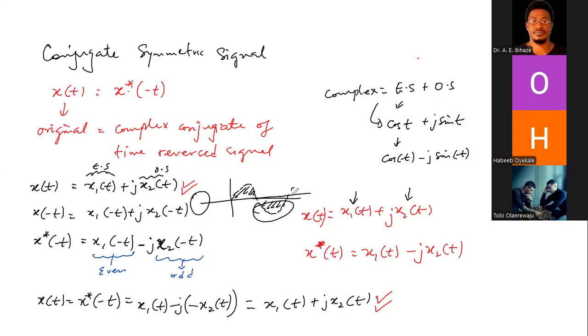When we do this in signal processing, we are conserving bandwidth, because we need twice as large a bandwidth to transmit the whole of this, while we transmit just half of the bandwidth for this. So if we get rid of this component, say the imaginary part, and transmit just the real part, we are able to conserve our bandwidth. We just use limited bandwidth to transmit the information we would have transmitted for the entire complex signal.